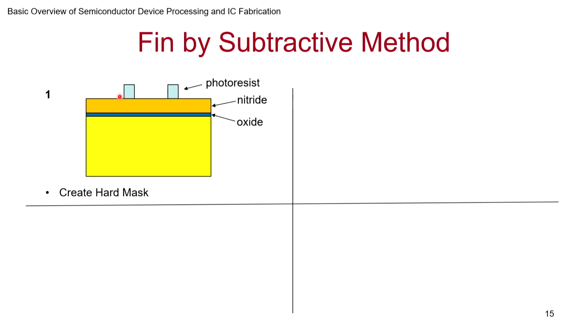So you do photoresist. Using photoresist, you do photolithography. Now with this photoresist and lithography, there are lots of tricks people have been trying. Double photoresist, that is, the pitch is often the limitation. So what you do is you have this, and then a second time you come and again do photolithography by doing exposure at this point and this point. So these are some tricks that they use.